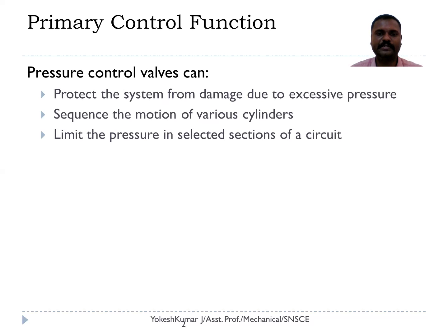One is to protect the system from damage due to the excessive pressure developed in the system. If there is any restriction in the flow due to blockage, the pressure inside the pipeline keeps on increasing, because the pump is continuously pumping the fluid.